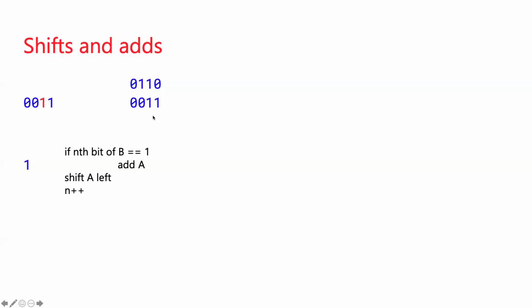And when I add that in, we could do the binary addition. 0 plus 1 is 0, sorry, said that wrong. 0 plus 1 is 1. 1 plus 1 is 0 with a carry into the next bit. That carry of 1 plus 1 is 0 with a carry into the next bit. And then that carry of 1 plus 2 zeros is a 1. I didn't really have to do that because it's right on my next slide.